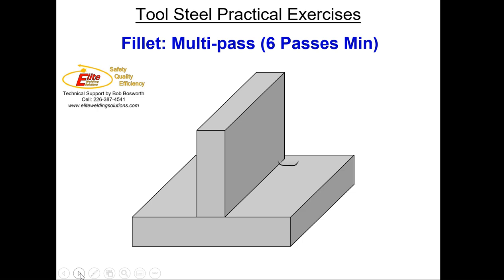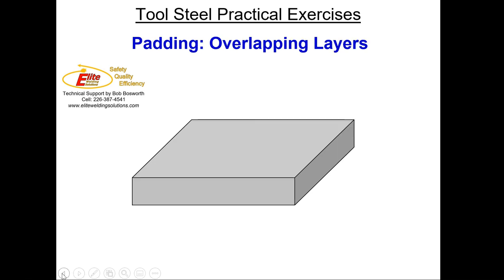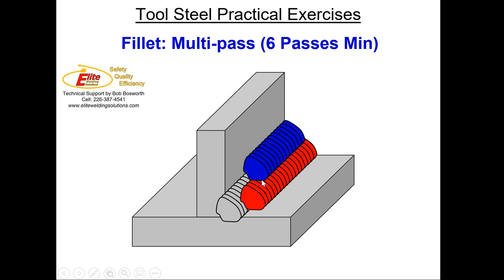So just a couple of more examples here when we're talking about our multi-pass welding. Our multi-pass welding represents building it up to the point where we can take it back to a machine and likely repair it. And that is, you might have to machine some of this out. But notice how I've done my multiple passes here. The first pass represents covering off everything inside the fillet corner. The next one represents an extension of the filler, extension of the leg. So we've gone out further, and the center of this weld is actually the edge or the toe of the weld underneath it. Same up here.